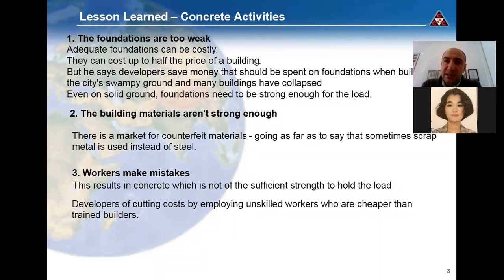So there are several steel rebars connected to each other, and that welded connection should be cut off. And then this cut element, the welded connection, should be tested in special laboratories, and again the results should be the same as the calculated results.